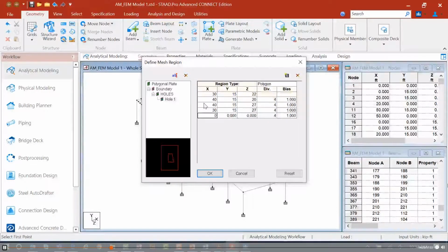And then finally, you're going to go back to your starting node. Okay. I know this is my overall slab area, and since this rectangular opening that I'm seeing here is appearing in my graphic, I do know that it is in the right location, or at least within the slab area.